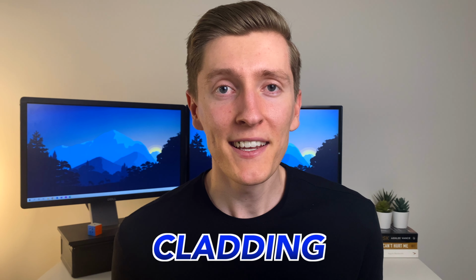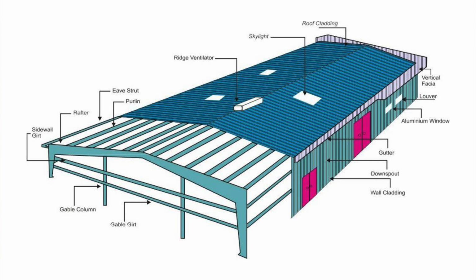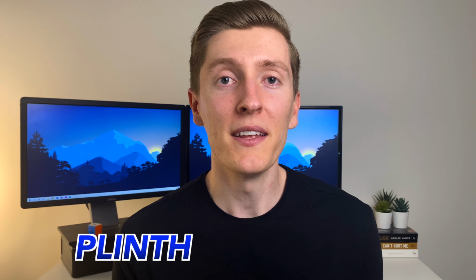Another element I was exposed to is something called cladding, and cladding is essentially the outermost material on a building like roof sheeting or wall sheeting. In my experience, the word cladding is more commonly referred to when designing steel structures, as elements that are restrained directly to cladding, like purlins or girts, have special considerations you need to make and are referenced in the design codes. Alright, and the last two elements are a plinth and a parapet.